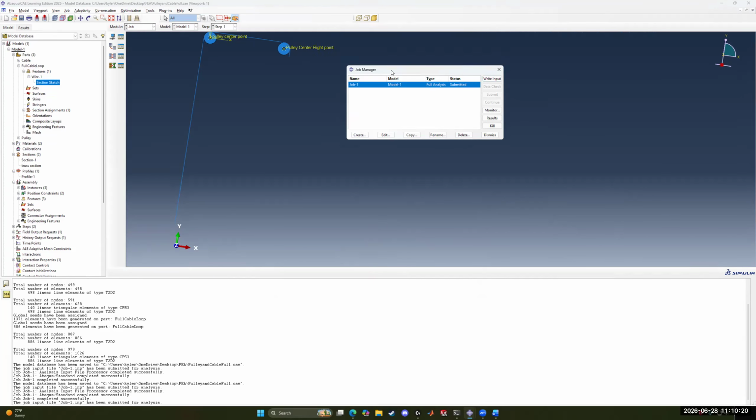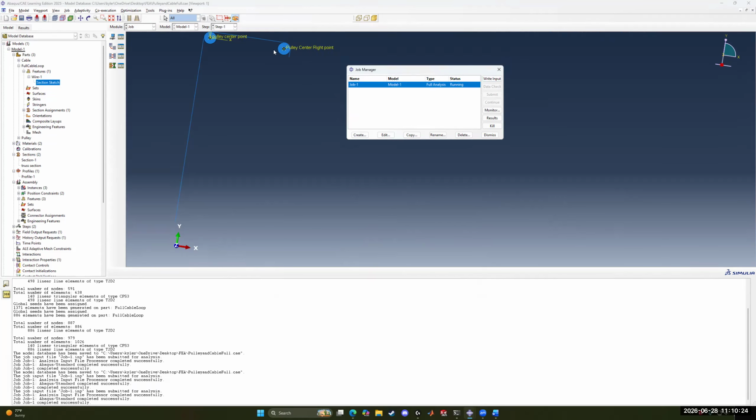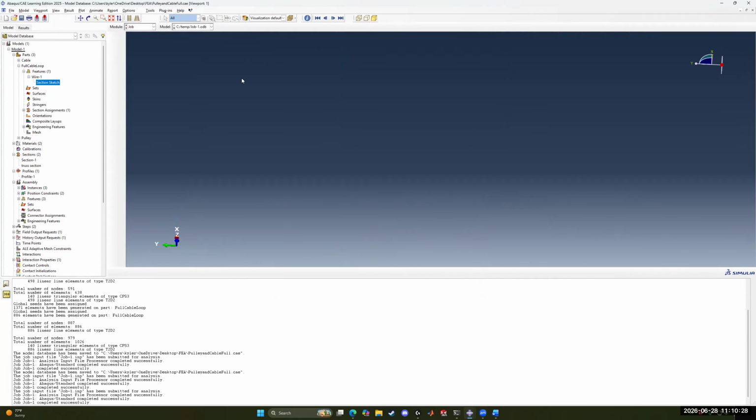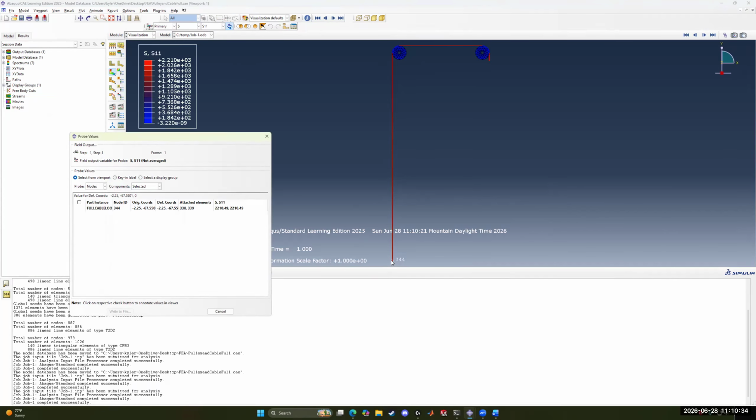The reason you can't use beam elements when using more than one pulley is because the beam bending doesn't show the axial load constant throughout the elements. So truss elements do a lot better at carrying that axial load. We can see that here. We go to S11, and we see the bottom left end shows the axial load as being constant in the part. The only problem here is it doesn't show the axial load carried throughout the bends themselves, but it does show here.